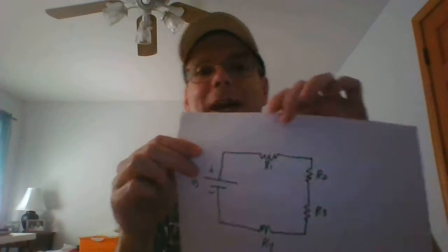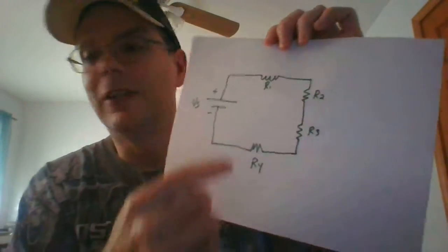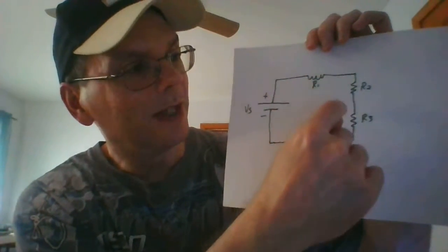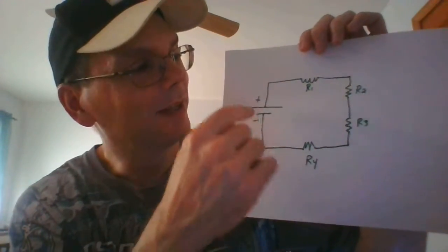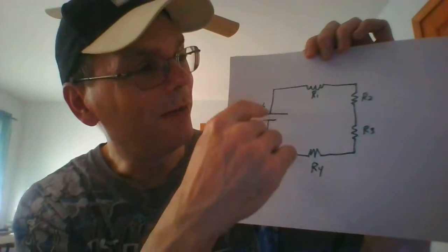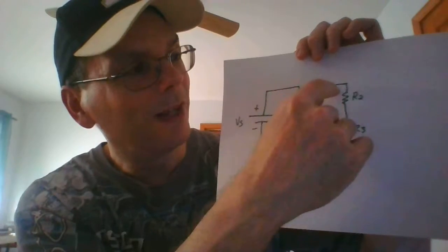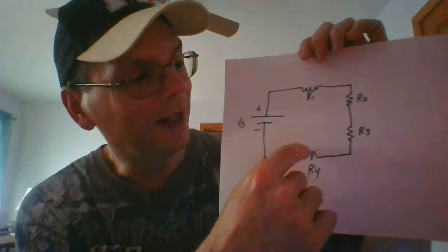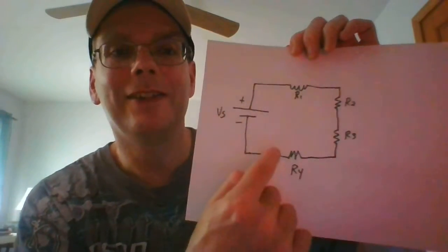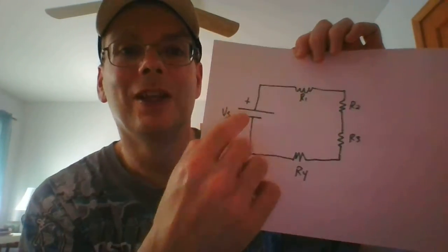So if we were to look back at our schematic, right, the voltage drops would be plus minus, plus minus, plus minus, plus minus. So if we, again, drove around our little electron car, we would have a negative value, a positive value, a positive, a positive, a positive, and we get back to the place we started. So these added together, subtracted from this, equal 0 algebraically. So there you go. You know everything there is to know about series resistive circuits.